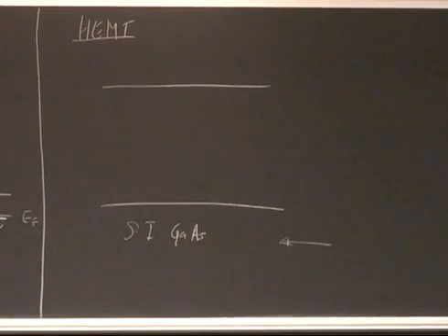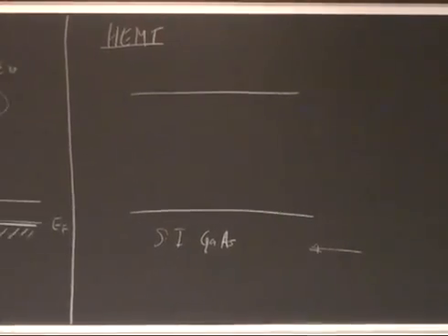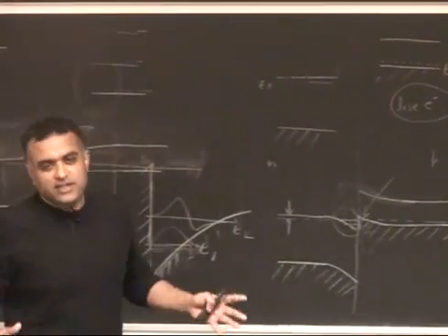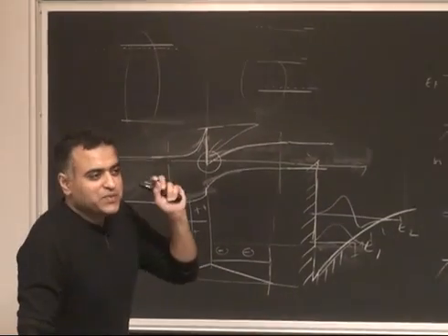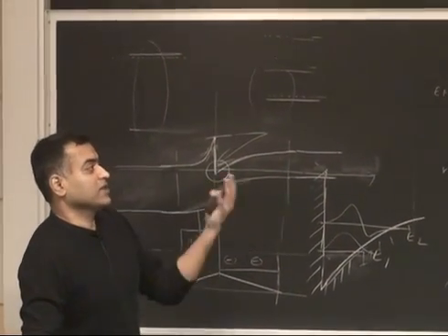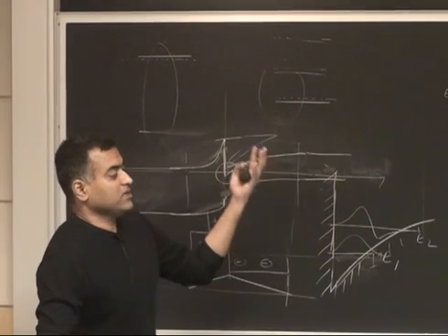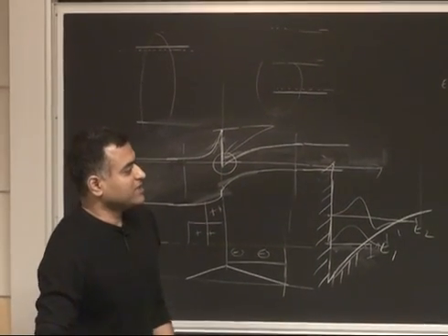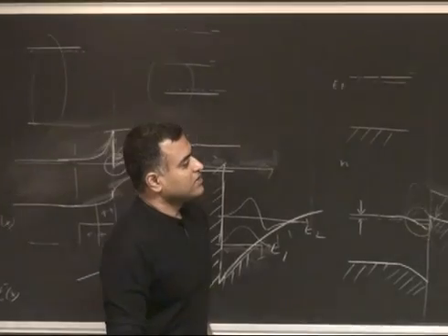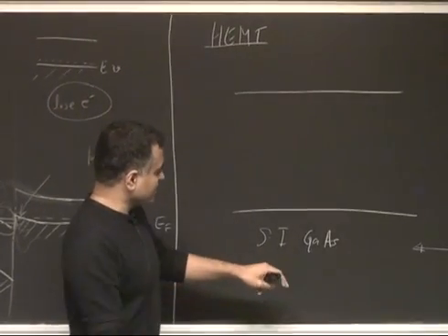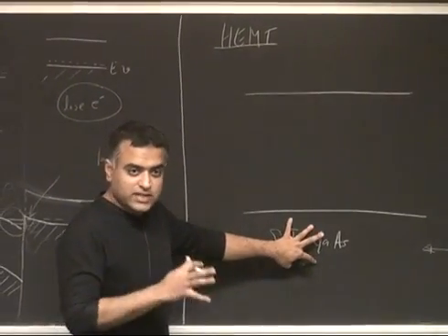This is kind of upside down from what you hear. You always hear, oh, high mobility, high mobility. High mobility is important, but it's not that important, right? Because with all the III-Vs, if you look at antimonides and arsenides, you can get 40,000 mobility, actually at par with many things that are claimed to be better, or even higher. But what is extremely difficult to get in materials is controlled insulating layers.